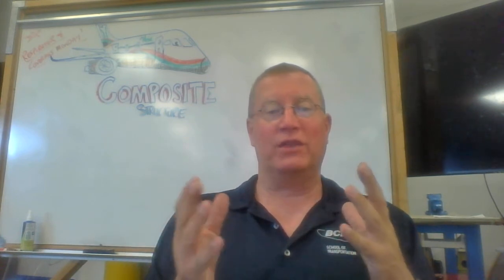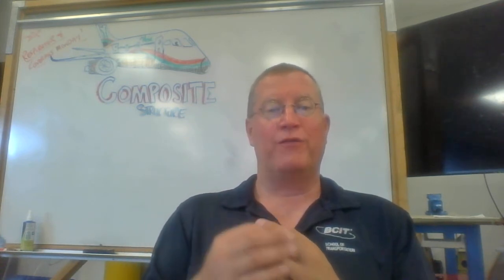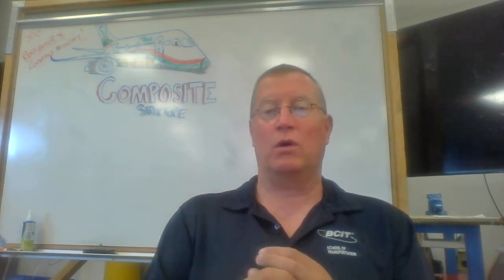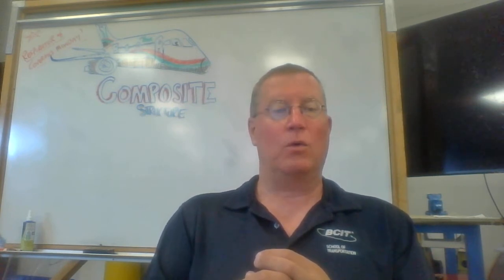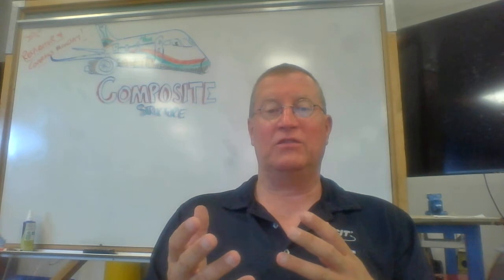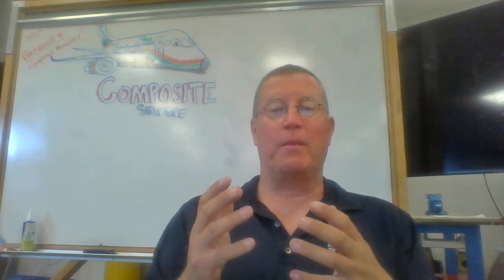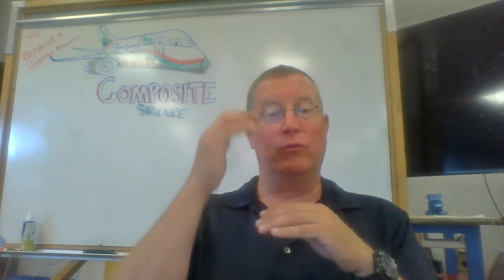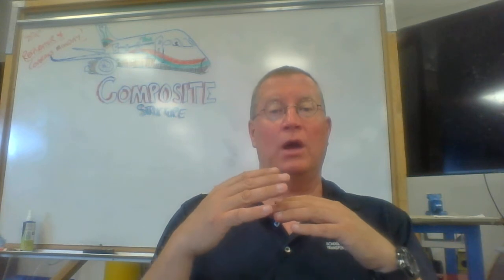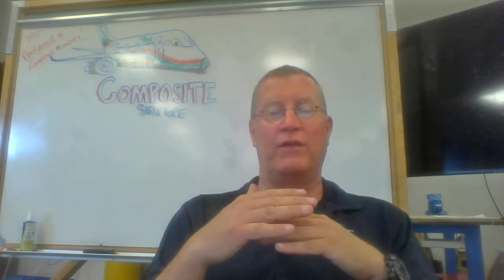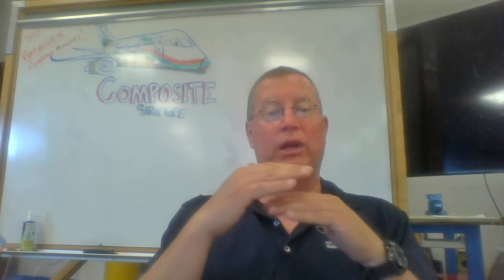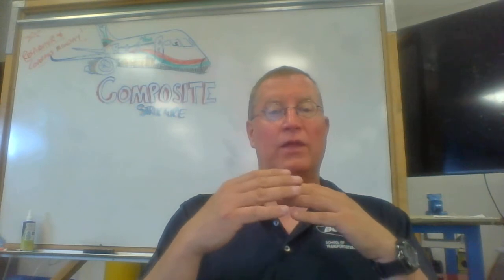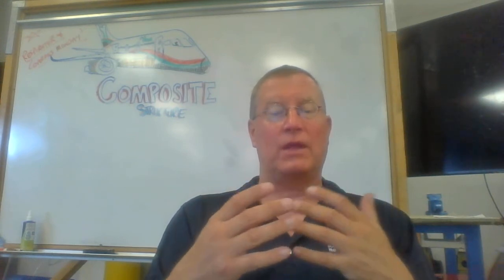If we think we have even the remotest chance of there being damage, the first quick and easy way of being able to tell, hopefully, will be our tap test, right? Either with a coin or a tap hammer. We're going to use that change in sound. Materials that are solid ring with a high-pitched ring, because the whole unit resonates as a solid mass, as opposed to the dull thuddy noise if you get a material that's been separated. When it separates, all those separated layers help to stop that ringing. They kind of deaden each other out, and so you get that dull thud.